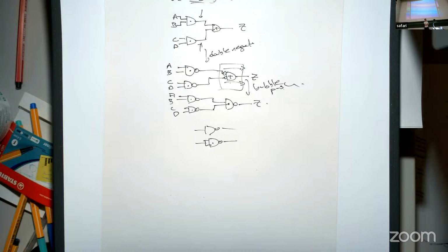Now, there's a bunch of instructions, like invert, which is the same, right? You're inverting it, you are actually using 2 registers. Is it an R type, or can I make it an I type where I don't care what the constant is? In the end, the architects, the people who are defining the ISA, may have more problems with one set of instructions, and they may realize that they need more R-type instructions, and anything that is not strictly 2 operands and 1 output, they will not use the encoding space of R-type. So they could have decided either way.